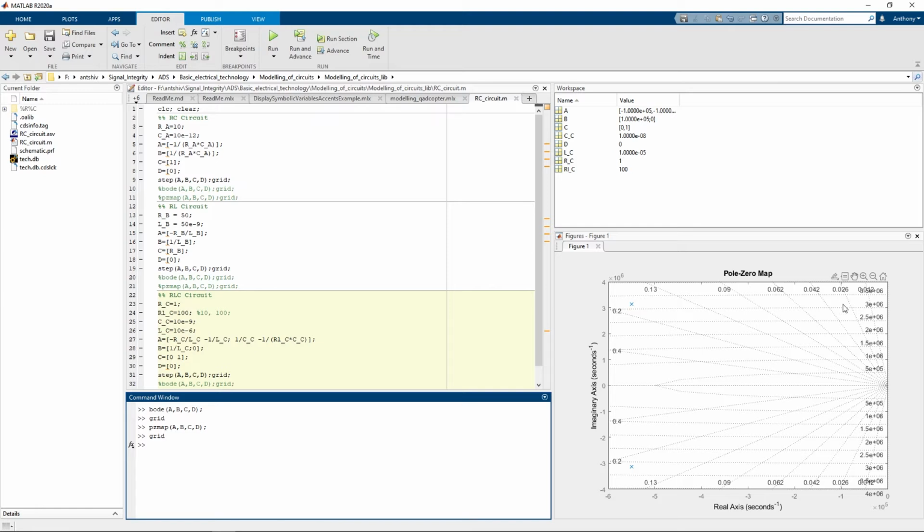And if there's anything on the right-hand side, that basically means that if there's a disturbance, the system will always grow over time. That will be an unstable system, but there's no practical system that actually works that way, because that would also mean that you're getting free energy. You disturb something and all of a sudden the system just keeps getting more and more energy. So you'll never have a right-hand side. It's an unstable system. It'll eventually break if the disturbance keeps growing.